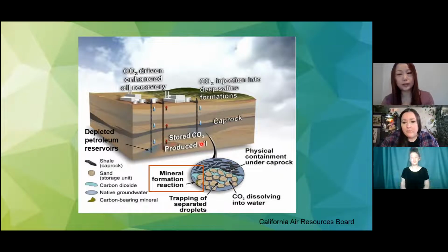Yeah, so this is another major issue where we really need to consider the caprocks, because our oil and gas reservoirs tend to be a couple thousand meters down from the surface, and our drinking water is typically way up here, a couple hundred meters below the surface, or even tens of meters under the surface. So as long as the caprock doesn't leak, we really don't contaminate everything above. We are not talking about the same rock layers at this stage.